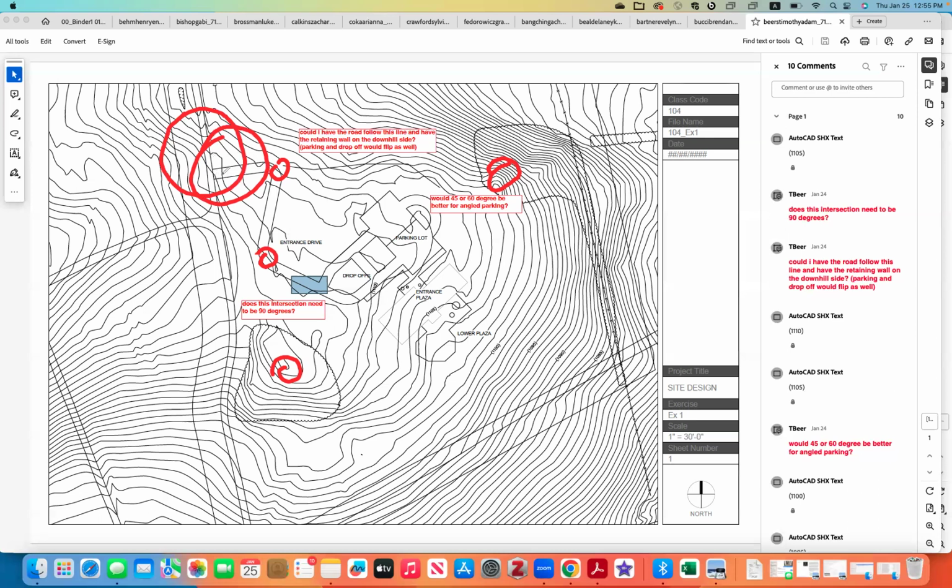I wouldn't kill this idea just yet. Measure this for this to be 100 foot. If this is below 100 foot, then no, right? Because you need to keep the entrance drive 100 foot from an existing intersection. If that's within 100 foot, I think this is still too steep for an entry drive. So I would still opt for some area here. About 100 feet here, this is pretty flat, and that makes it a lot easier for you to do the entry drive.